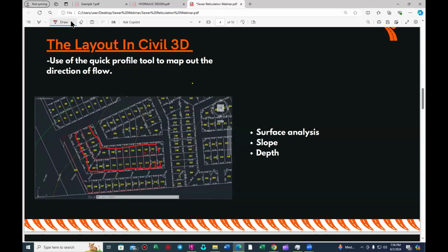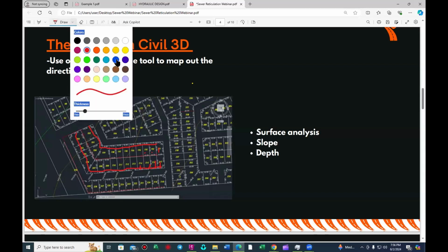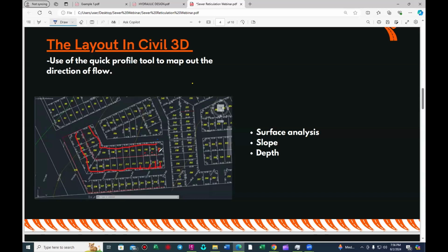But you'd realize that your project now becomes very expensive, because rather than us laying one common pipe here that will service both the stands on this side and the stands on that side, you are doing two separate sewer lines. And laying sewer lines is very expensive. You need to lay out your manholes. Your manholes are made of what we call precast concrete. They're expensive. Your pipes are expensive. Trenching the pipes is expensive. Doing the pipe bedding is expensive. So it's an expensive process. So rather than that, we just have one common pipe that we lay in between the blocks of those stands. So that's a common way.